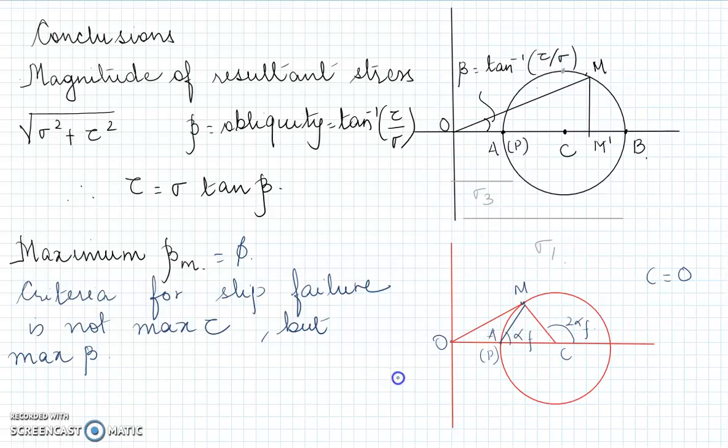That's why there is a limit at which you can cut a hill. You can't cut it too steep. Why? Because it will fail when the slope has reached its maximum value. Okay? It is very clear that the failure will occur along the plane Pn. So I have drawn here Pn. This is the plane at which failure will occur, and Pn is called the critical plane, or it is also called the failure plane.